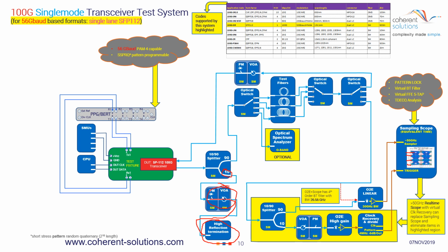For instance, if this VOA is set for 5 dB of attenuation, the signal will have 5 dB of attenuation going through in this direction, and once it reflects back, it will have another 5 dB of attenuation coming back. So ultimately, we'll have at least 20 dB of attenuation, 5 from a double pass to the VOA and another 10 dB approximate because of this small percentage here.